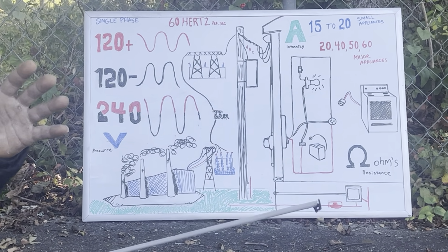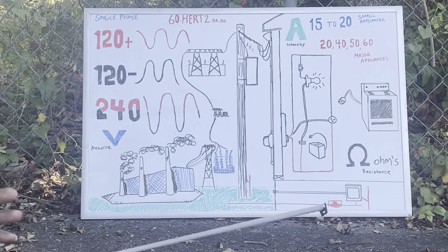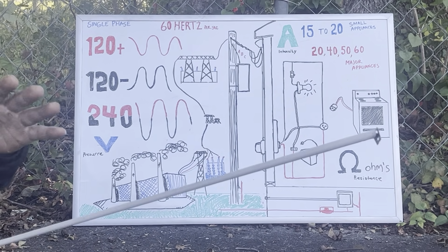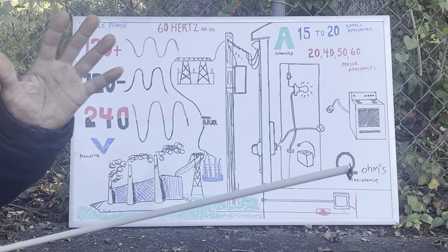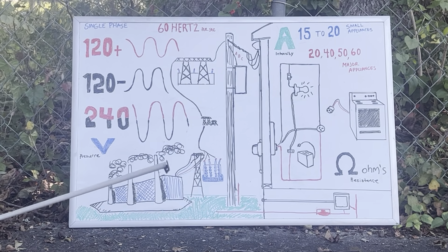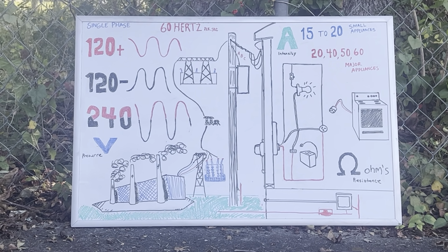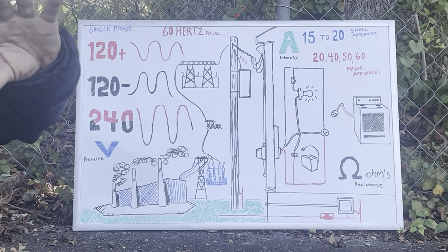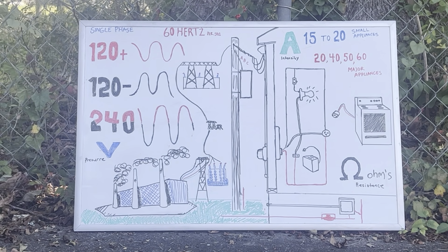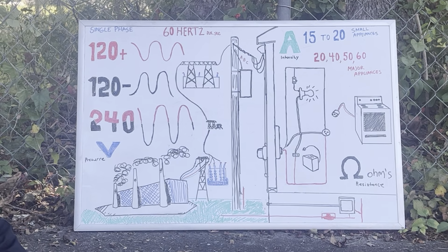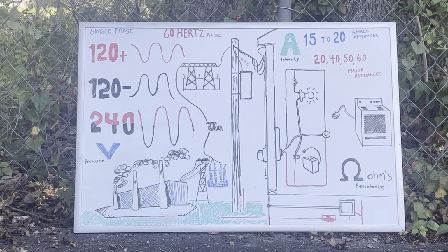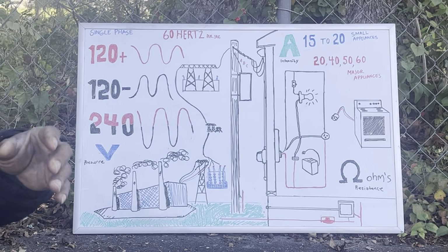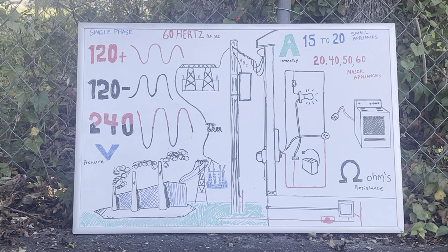Now your coal went from chemical energy to thermal energy with the fire. Then you moved on to mechanical energy dealing with the turbines, the shaft and the generator. So that's mechanical energy now. In the generator, you've got copper coils in a magnetic field. Usually you have three-phase generators, which basically means that these copper coils are offset 120 degrees, okay?